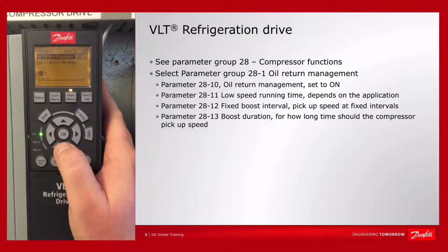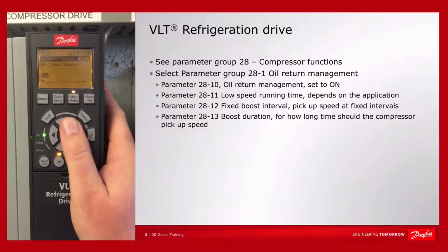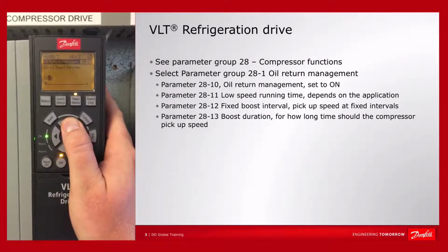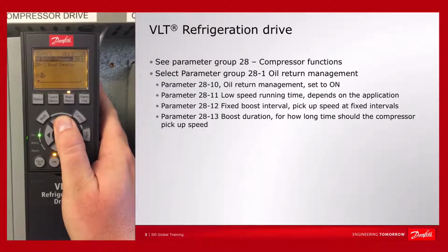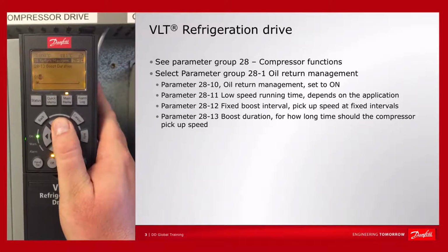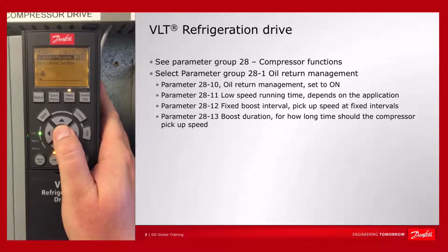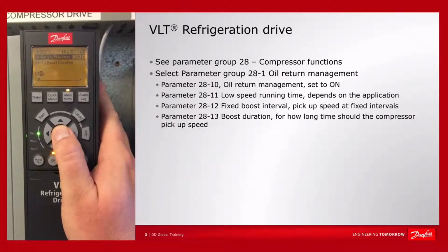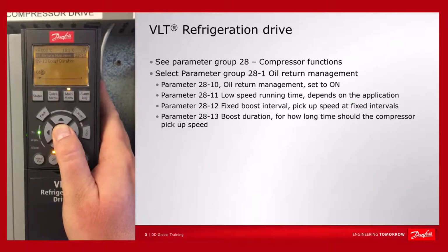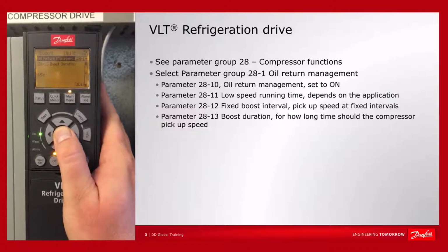I'll put 15 seconds, but this is also system dependent on how long it must run at this particular speed before sufficient oil is returned to the compressor. It could also be up to 2 minutes, but in this small system 15 seconds would be okay.